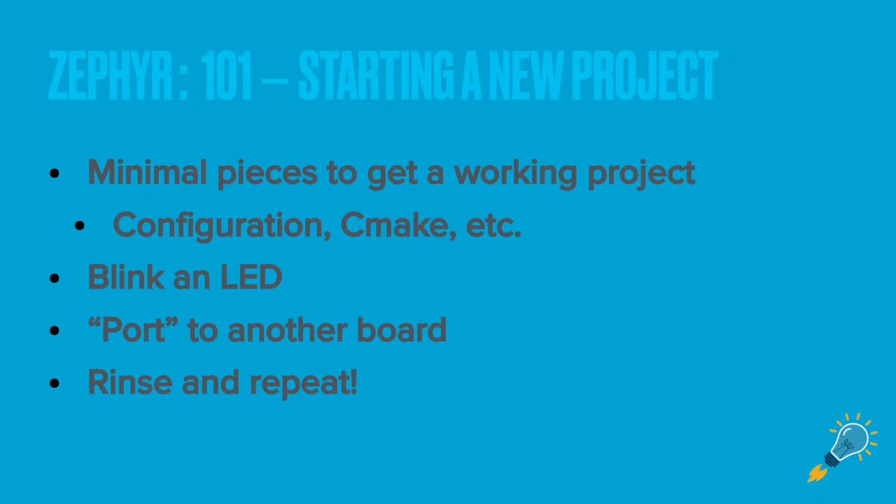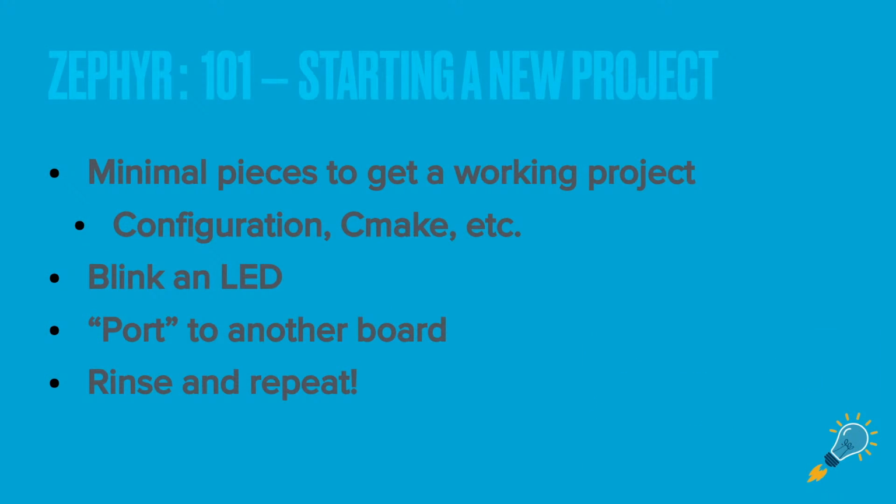One thing that's different in Zephyr versus maybe another RTOS is that if you have it set up correctly, there's no porting per se. There are some board definitions that define what your hardware is capable of doing. But beyond that, the ideal situation is you can use the same code for one chip as you can for another chip, across vendors, across modules, across everywhere. That is the power of Zephyr. And there's added complexity to that, but once you get the complexity, you'll have a better idea of how it actually works.